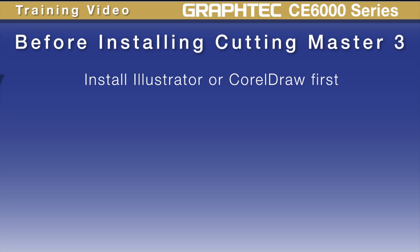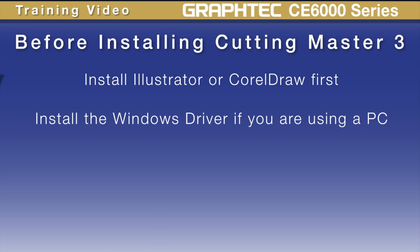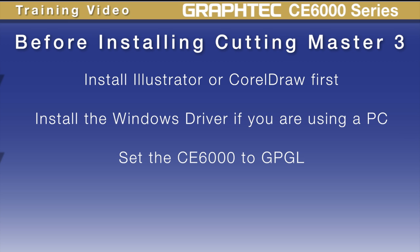While Cutting Master 3 doesn't need or use the Windows drivers that came with your cutter, it is always a good idea to install the drivers. This eliminates annoying plug-and-play messages appearing later on. Since Cutting Master 3 outputs to Graphtec's cutter language, known as GPGL, the cutter will need to be set to GPGL mode. This was covered in the installation and setup lesson of this video. If you're not sure how to do this, review that lesson or look in your manual.